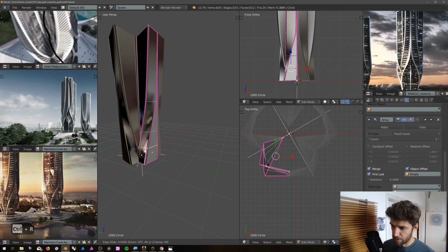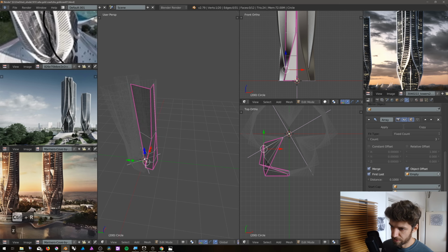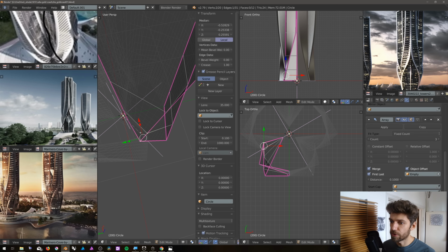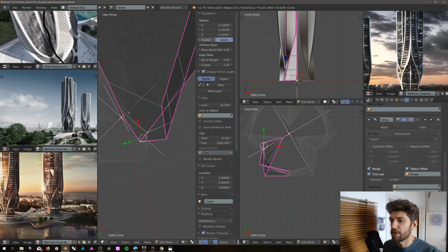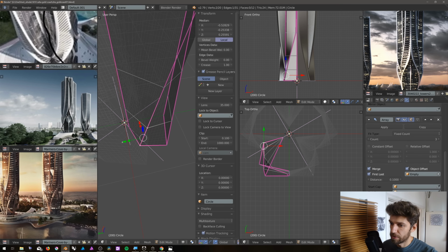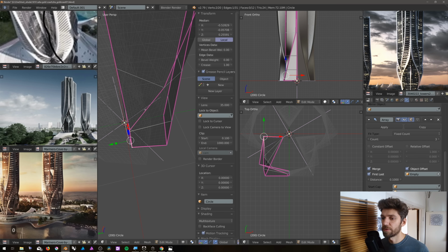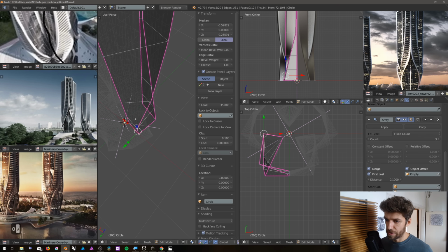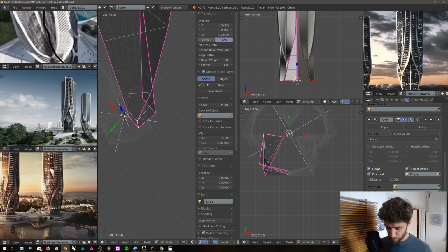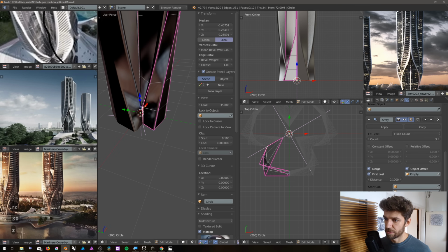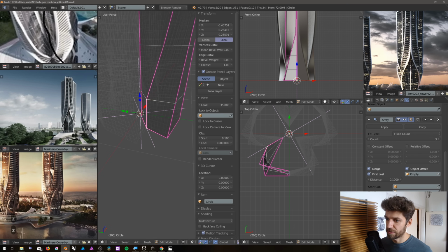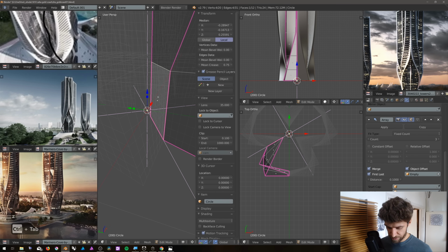Cool. Alright, now it's time to do a bit more loop cuts. What I'm going to do is rotate them exactly along the axis, because right now I know where they need to be. It's not where I want them to be. So I'm going to move them along this axis. Scale that, what's this? That's the y-axis. Scale the y-axis to 0. Change the y value to 0. And now if I use my central pivot point, I'm going to rotate 30 degrees. Now I know it's exactly on axis. That's important because we want that to start merging.